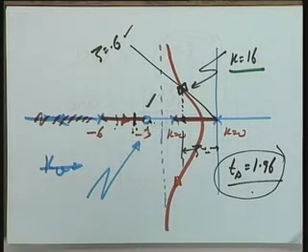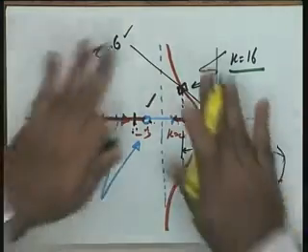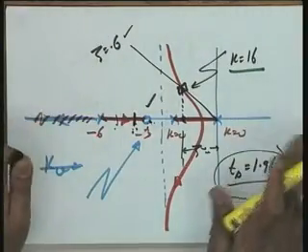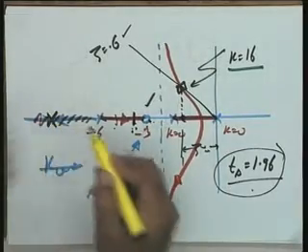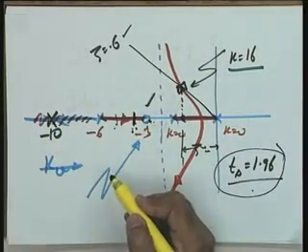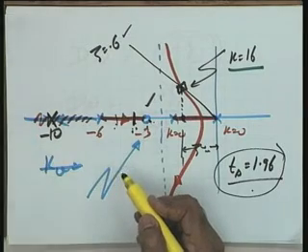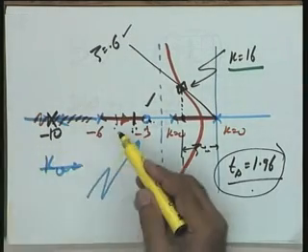So what you will do is place the pole so that as far as the root locus sketch is concerned, it is more or less the same, and therefore I place the pole far away, maybe at minus 10, minus 12, just depends upon the realization requirements. Many times you can say that far away means minus infinity.